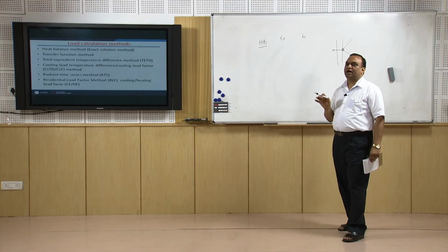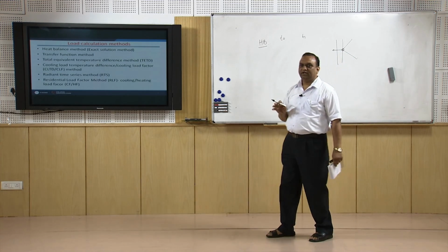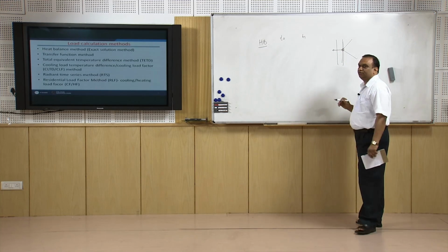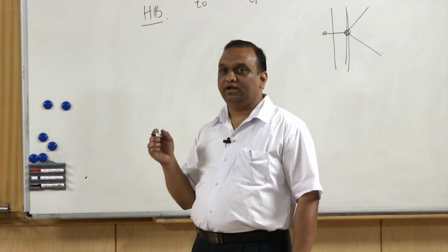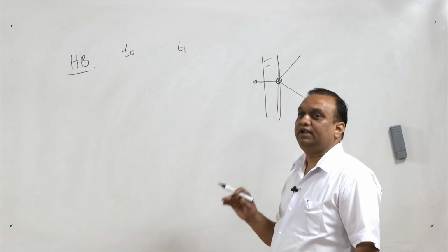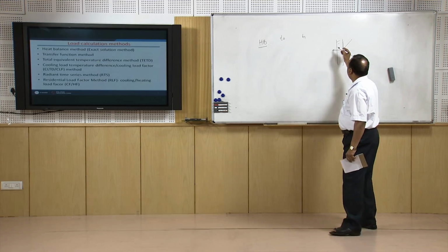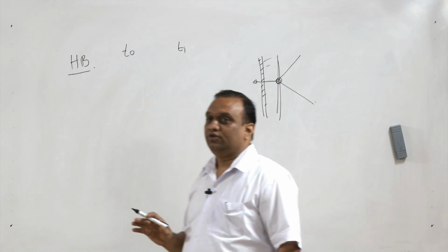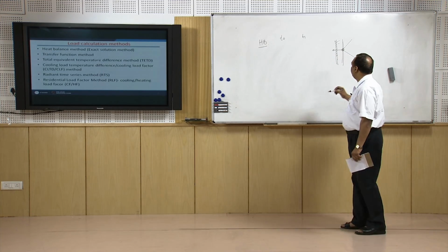Now if you look at the architecture of the old buildings in India, we have heavy type of construction. If you go to Europe or the US, you will find light type of construction. They have light construction because in their buildings most of the time they do heating. In order to save energy, they prefer to have lower thermal capacity of the building so that when heating the building, minimum heat is absorbed by the building. At the same time, the entire building is insulated. Wall insulation, roof insulation, everything they do so that heat loss from the building is minimum. Heat loss means there is a loss of energy.